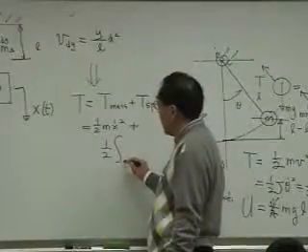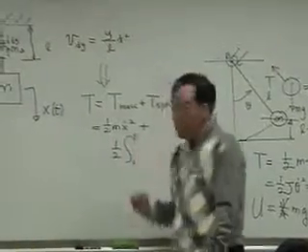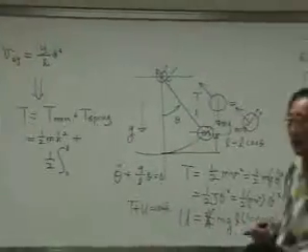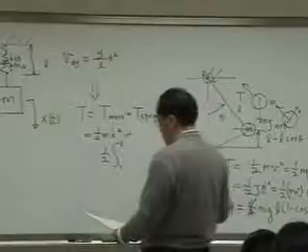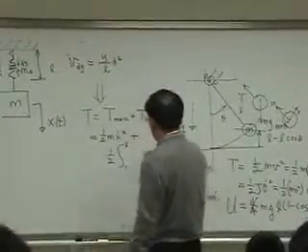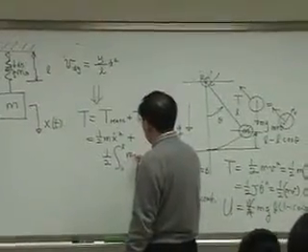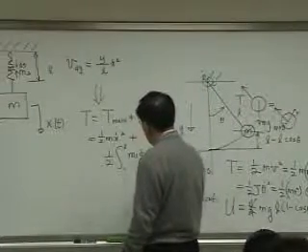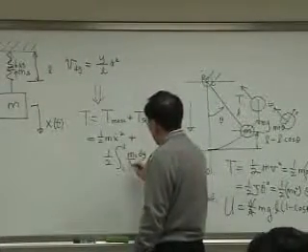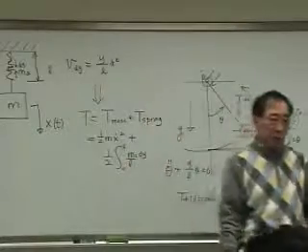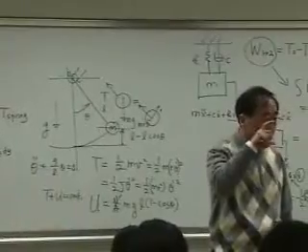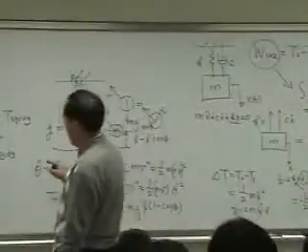I'm integrating from 0 to L because the spring is distributed from 0 to L. And the mass of the spring is ms, and the dy over L. ms is the total mass of the spring, and ms over L is mass per unit length.